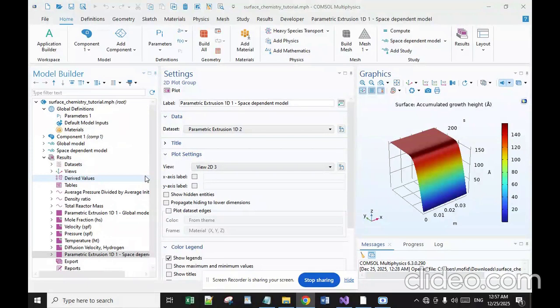CVD oxide invariably has lower quality than thermal oxide, but thermal oxidation can only be used in the earliest stage of IC manufacture. Oxide may also be grown with impurities, alloying or doping. This may have two purposes. During further process steps that happen at high temperature, the impurities may diffuse from the oxide into adjacent layers, most notably silicon, and dope them. Oxides containing between 5 to 15% impurities by mass are often used for this purpose.